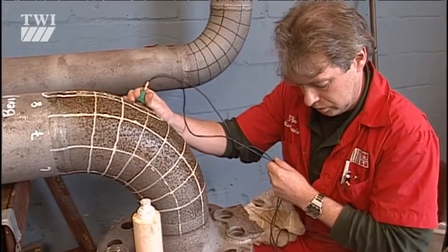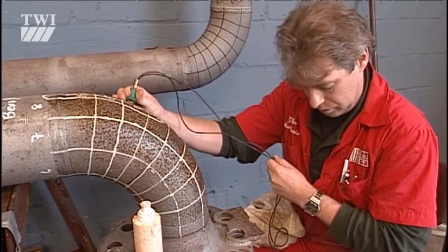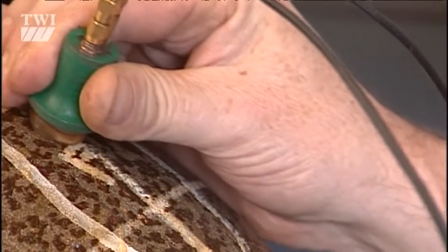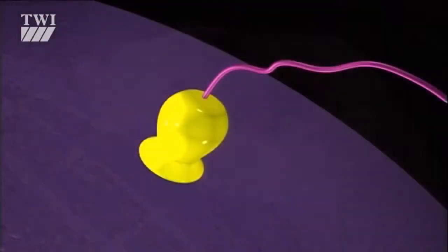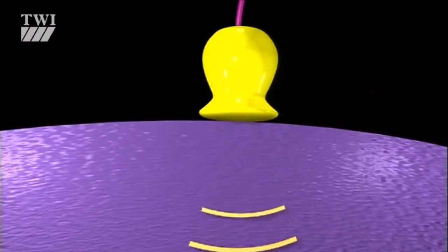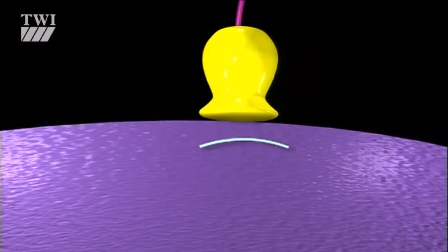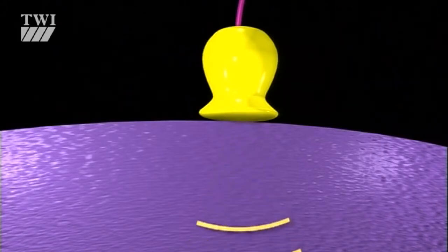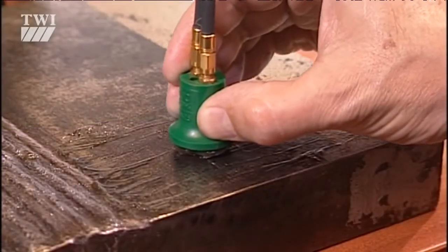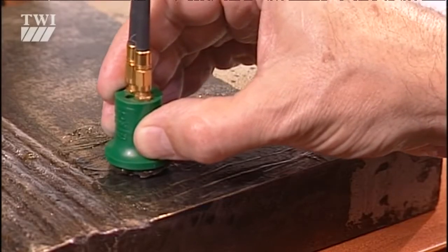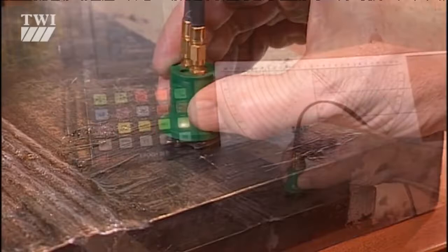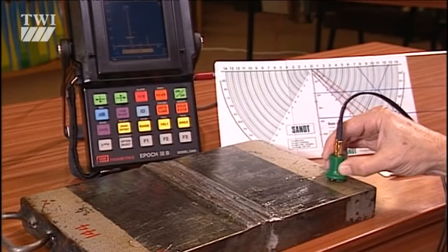Well, now let's look at ultrasonic testing. UT, as it's known, is actually a generic title for several different methods of generating and observing ultrasonic signals. They're all different, but use the same basic principle. They all use a signal above the audible frequencies, hence the word ultrasonic. This is passed from a probe into the component under investigation. The signal bounces or is reflected when it comes across a discontinuity.